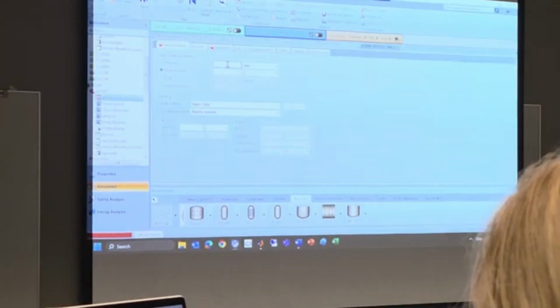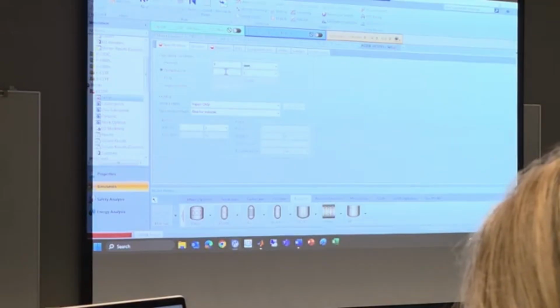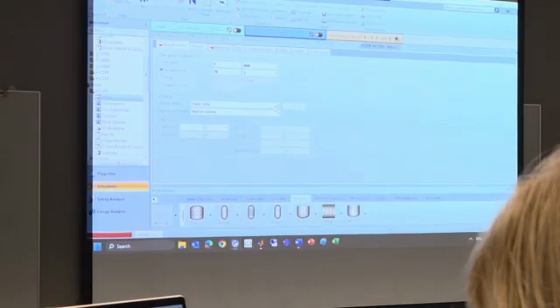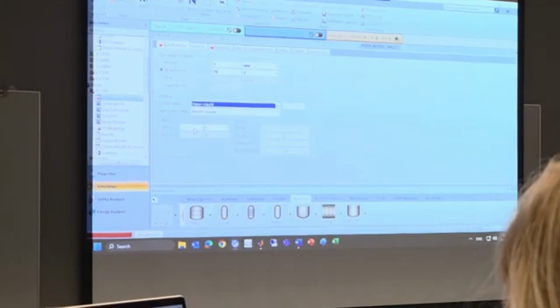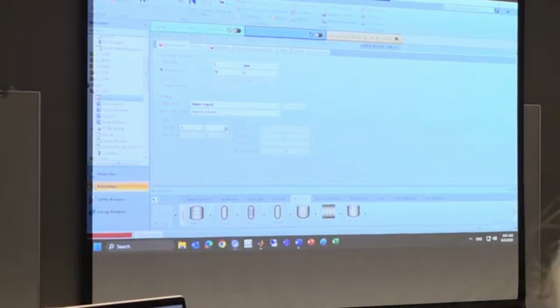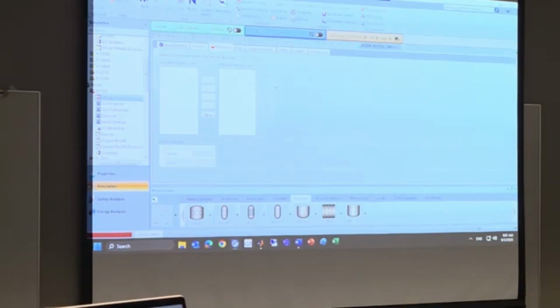If you click next, we can choose the same 180 and 70 degrees Celsius, valid phases vapor-liquid. Reactor volume may be 1 cubic meter. Then if you click next, we have to define reactions.